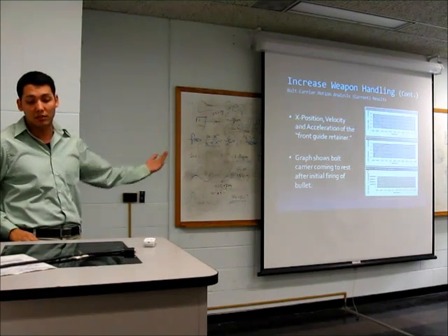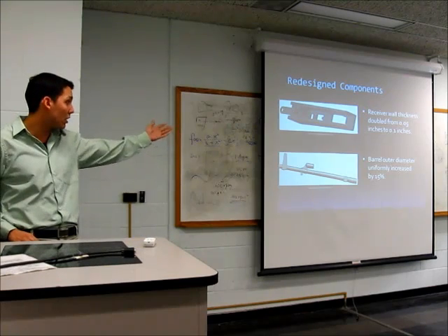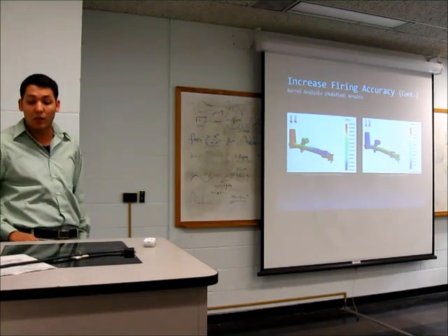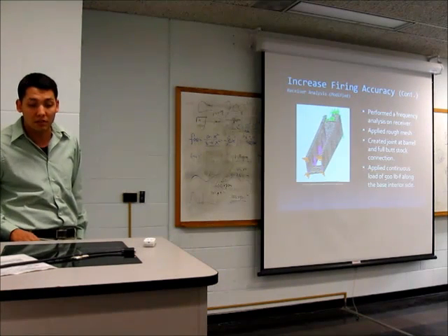I have position, velocity, acceleration there. Redesign components, same thing: increase the thickness of the wall here, increase the thickness of the barrel, did the same analysis. You can see there's a displacement of only 1 inch as opposed to 1.5 inches, and I reduced the stress in the barrel significantly.